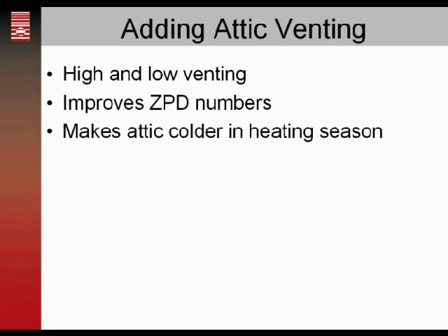A little more about attic venting. Again, what was mentioned before was that low venting is important. Otherwise, if you only have high venting, if you only have a ridge vent or high roof vents and no low roof vents, then you're just venting out air that's leaking into the attic space. That's where it's getting its intake.